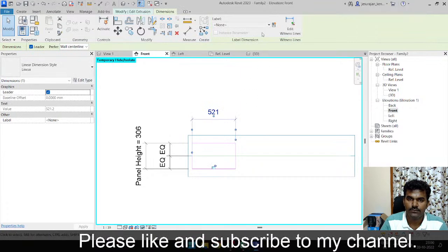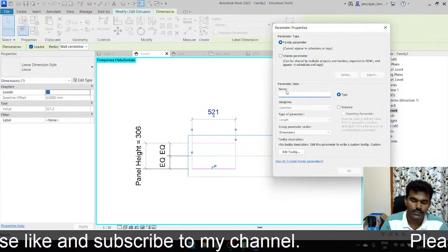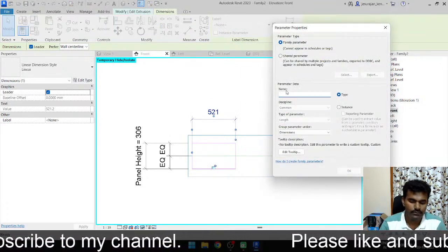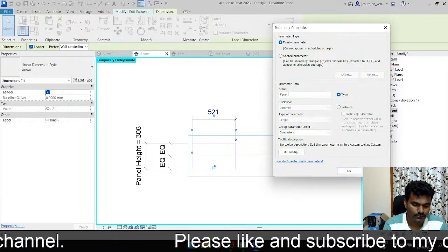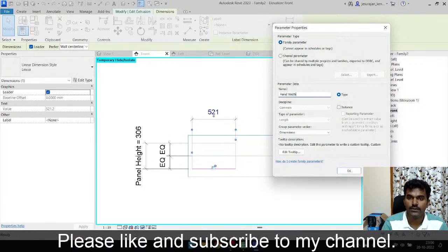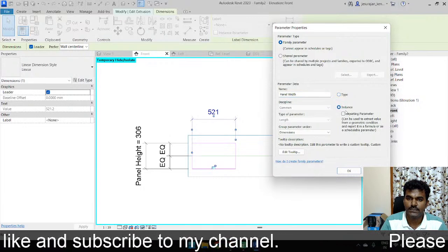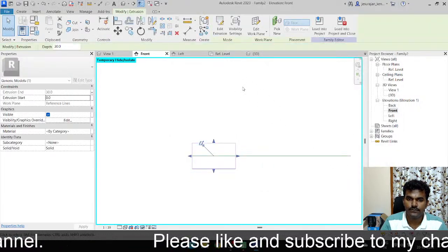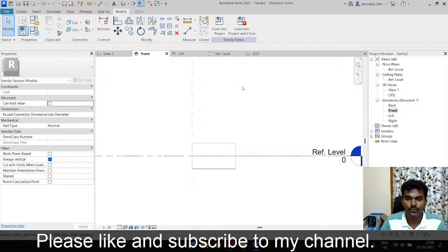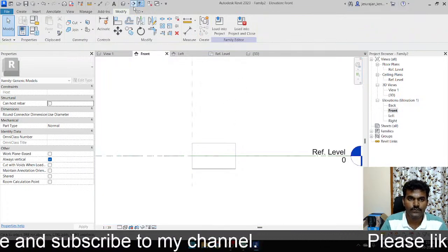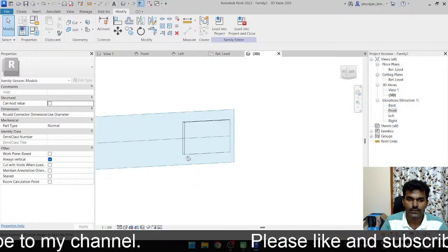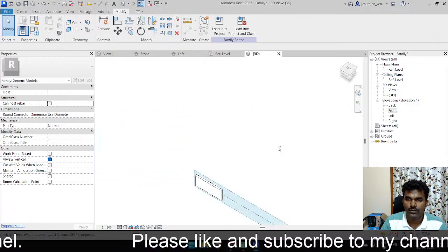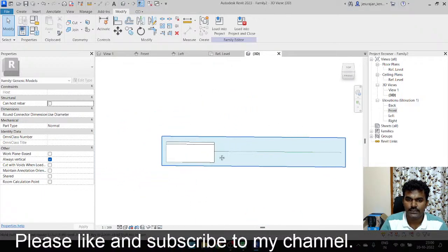Select this dimension, create a parameter, call it panel width. Keep this as instance. Okay, finish. So now we are going to check our parameter. Go to 3D.